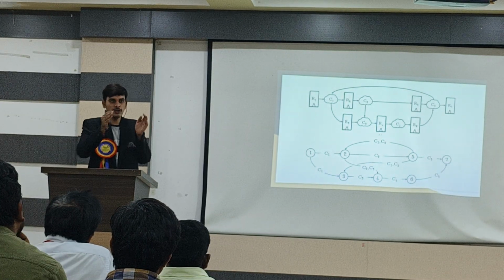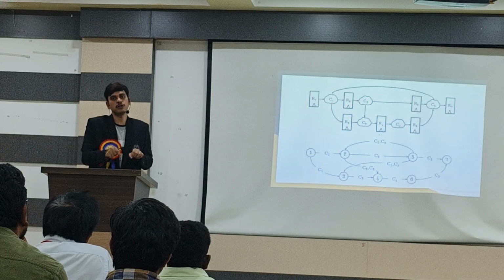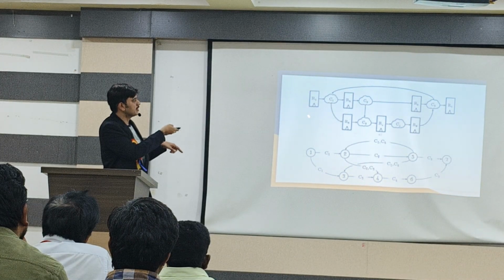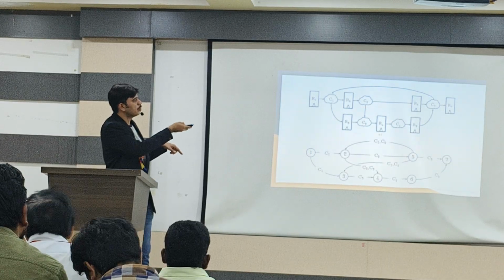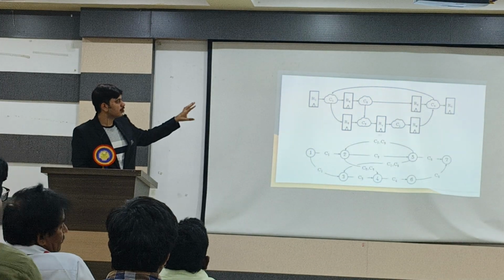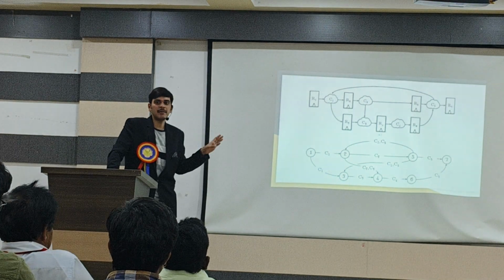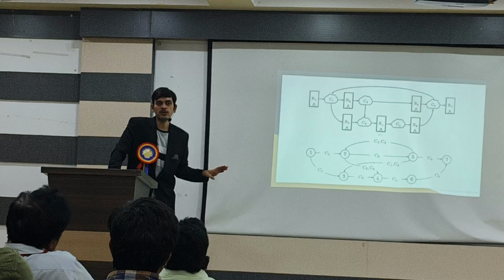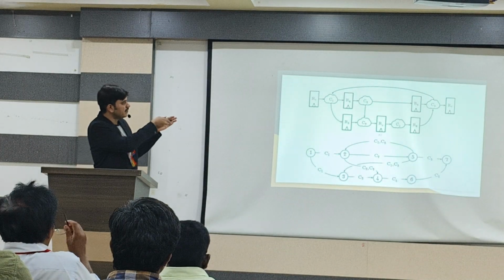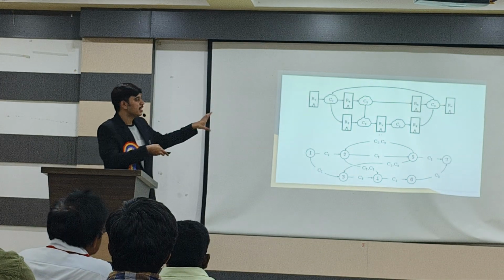So between blocks, you have to close the timing, and internally, the register logic also you have to close the timing. So these are register to register, and input to output also. When we go to the calculation, we see the setup and hold, right? Basically, timing is based on the setup and hold. So based on the equations, we close the timing.